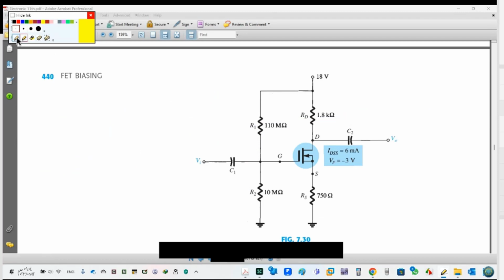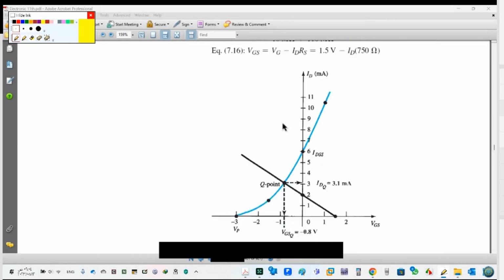See this here? Same thing, but we have this, so take care about this part. I drew it to you. Then you can continue to use the same formula that I gave you for the voltage divider configuration. Same thing exactly, just in this case the transistor can work in this positive area in enhancement mode. Okay.